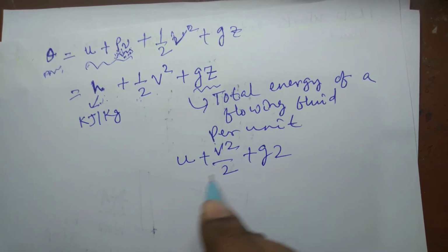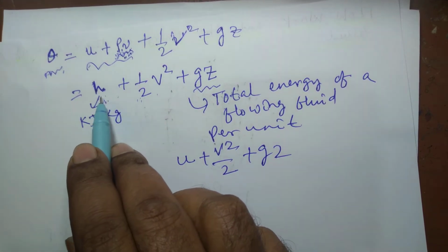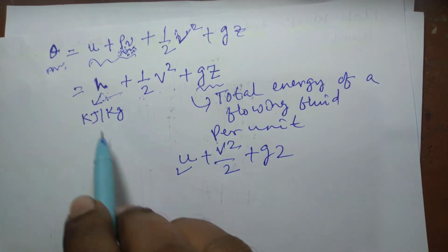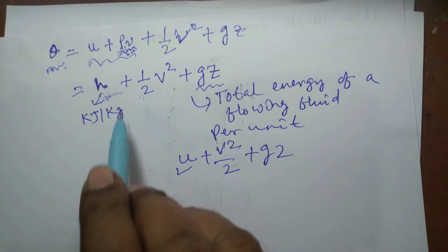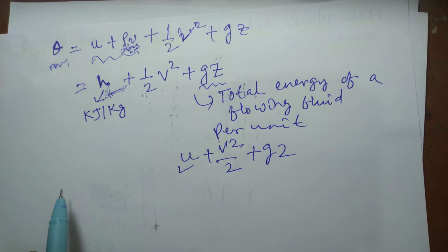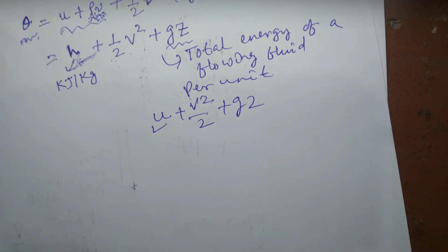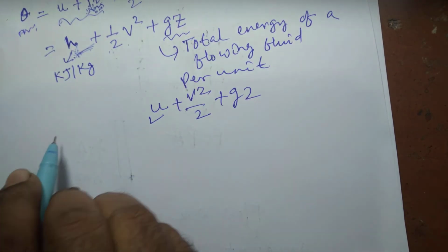This is the difference. And in the case of a flow system, h will be there in place of U, and this h simply takes care of the flow energy or flow work and nothing else. So once you take enthalpy into consideration, your flow work concept is taken care of. There is nothing to be worried about regarding flow work once you have taken h into account.